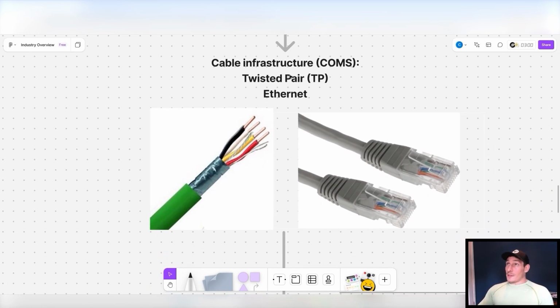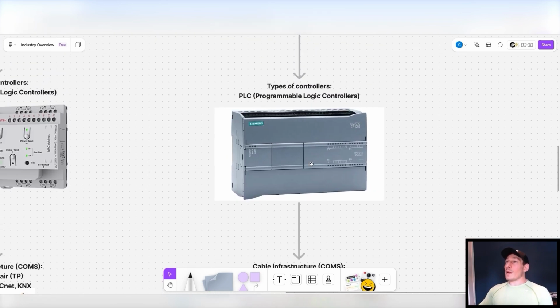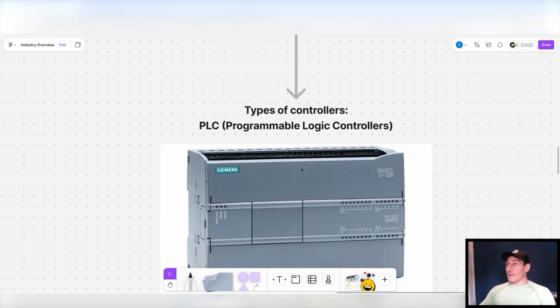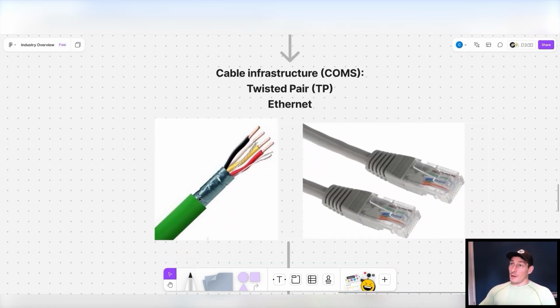And in terms of cable infrastructure, and again, just sticking with the comms, when you get into process control, it depends on how modern an installation you're working with. It could be older style twisted pair, or newer modern systems like Siemens using Profinet, I think it's called. They're communicating across Ethernet.